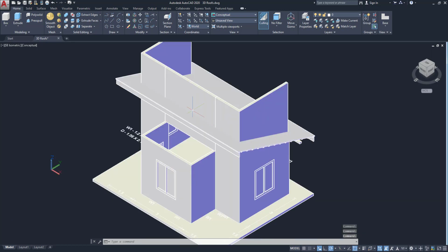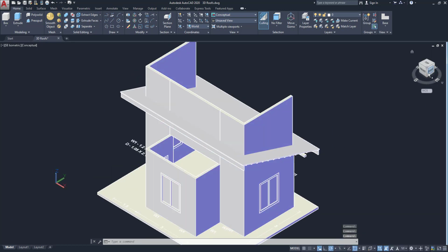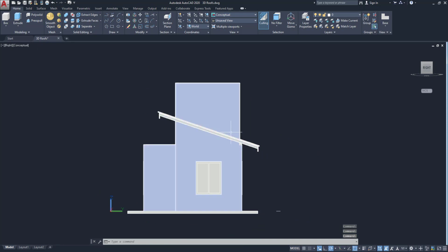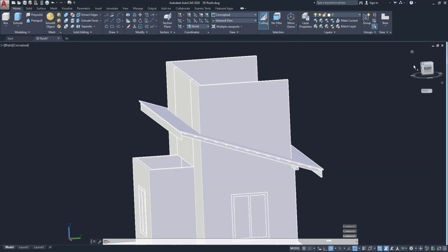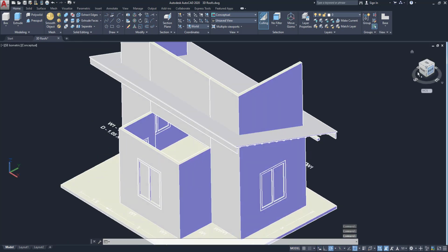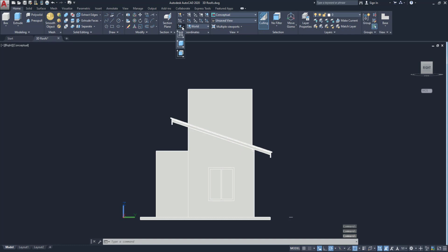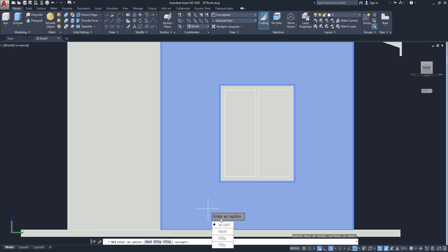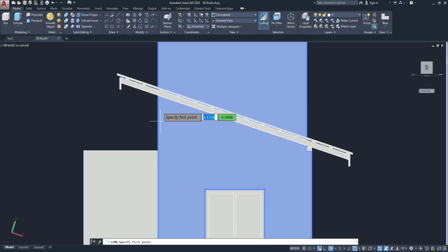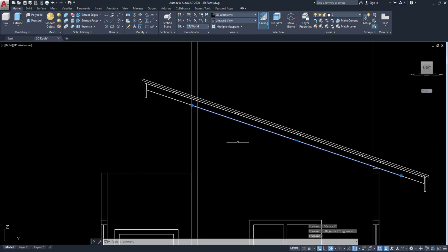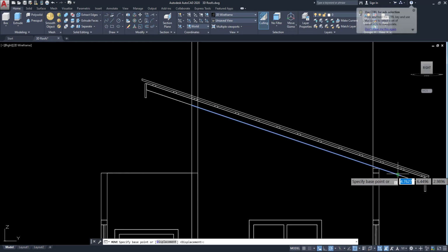We have extruded. We are going to slice this part. So this is the easy way. Go here and somewhere around you have to place a slice plane. So go to right view and go to face. Click on this face, accept. So the face is created. Now I am going to draw a line. This line will be a slice plane.